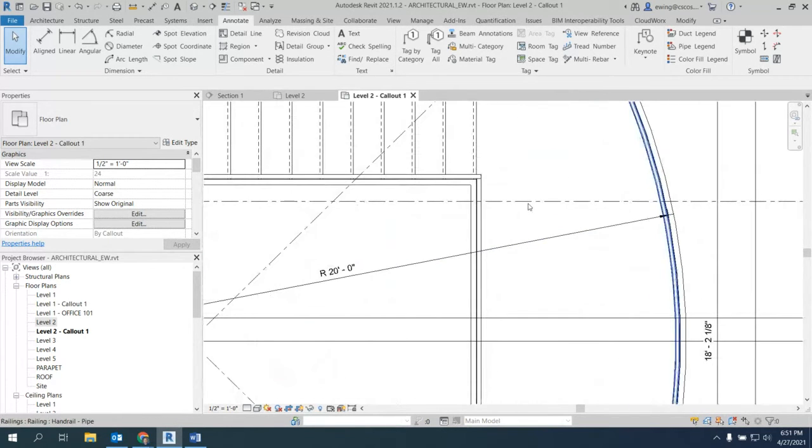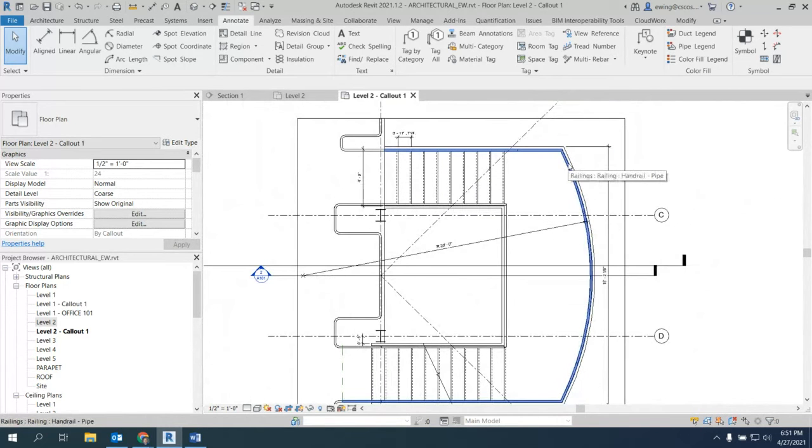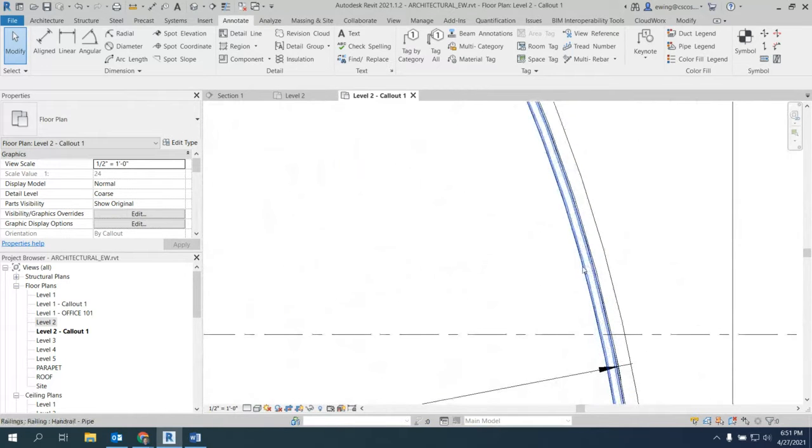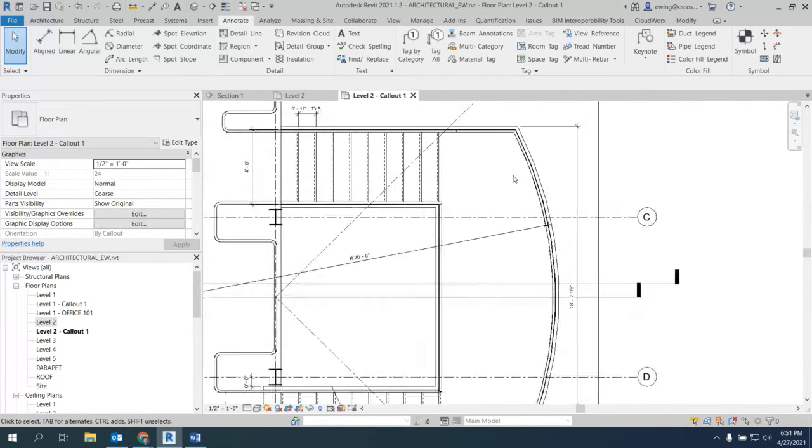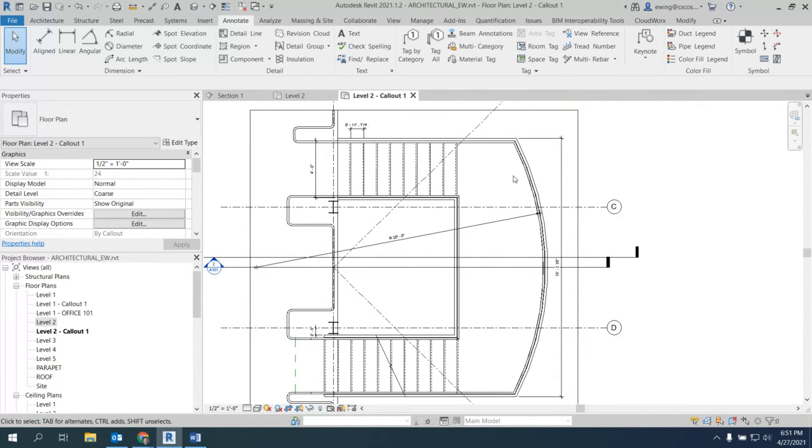And that's exactly what we would do. If this was a wood staircase, we would have probably built this on site. We would have had an area where we had to lay this out, and we would actually snap lines on the floor and draw that and actually make it to be those dimensions. Sometimes we'd rather do it on site because it's an unsettling feeling when you have a truck loaded with all these prefabricated parts and you get there and the actual dimensions aren't exactly what they were back in Syracuse. Sometimes it's a better feeling just fabricating it on site, but that kind of dimension is important.